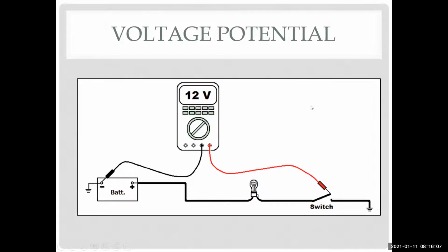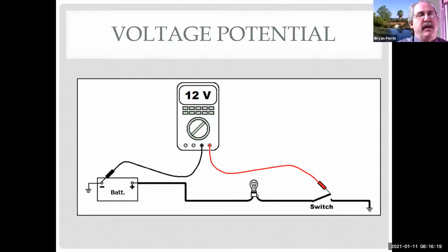In this situation, when you have the switch closed, the voltage would be 0 because the current has gone through? Yep, it should be 0 because the ground on this side of the load should be electrically the same as the ground at the battery. Question, Mr. Jackson. Mr. Brian. It's 12 volts passing the bulb, then goes to the switch. Switch is open. There's no ground.